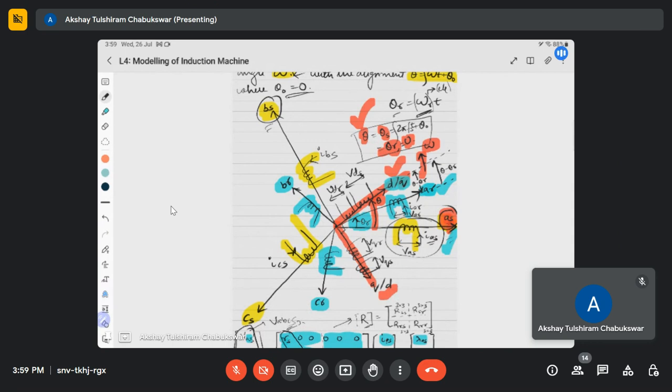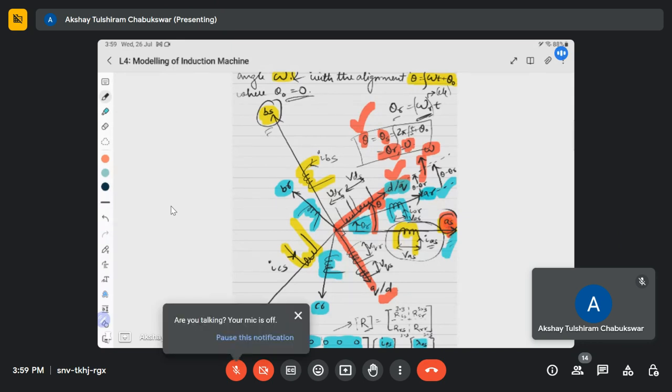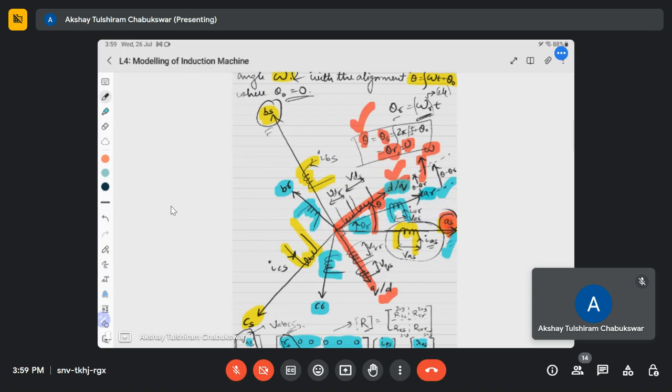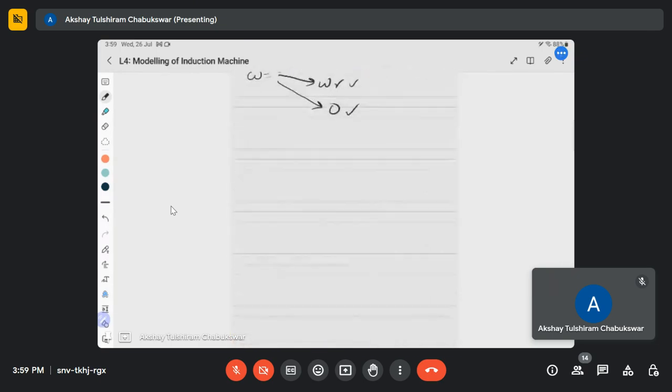But for other AC motors like a permanent magnet synchronous motor, or a synchronous motor, salient pole or cylindrical, you can't model the motor in any random DQ reference frame. In that case, you have to model the motor in the rotating DQ reference frame; then only it is advantageous. But it's not the case in an induction motor due to the symmetry. You can model the induction motor in any arbitrarily rotating DQ reference frame with any convention, because you will get constant matrices in all the cases.